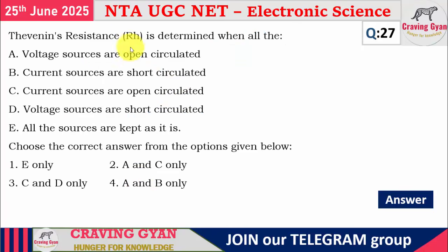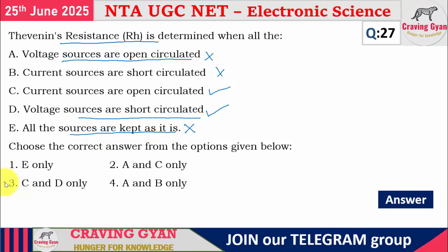In the 27th question, in order to find the Thevenin's theorem, what is the precaution or arrangement you are going to make? We are going to take all the voltage sources as open circuited. It is wrong. We are going to make all the voltage sources short circuited. This is correct. And all the current sources are open circuited. So all the sources kept as they are is wrong. So C and D follow. Option number 3 is correct for the 27th.